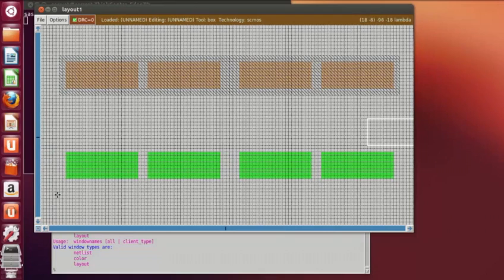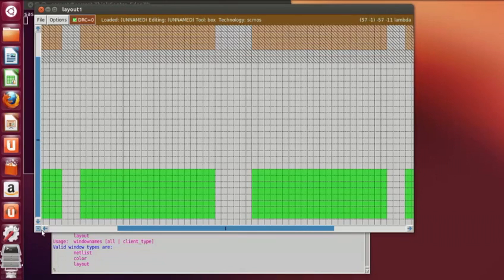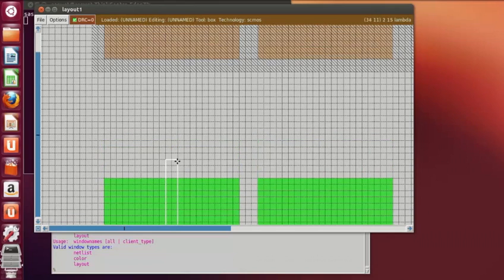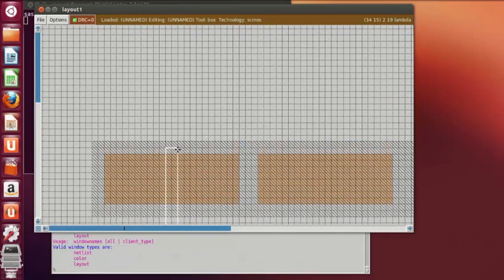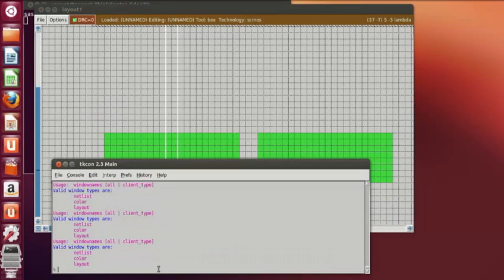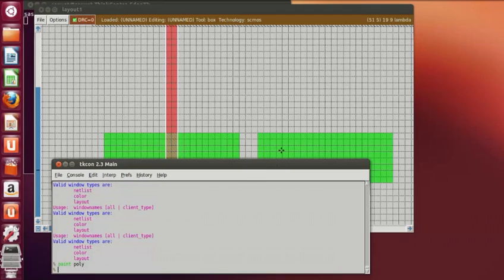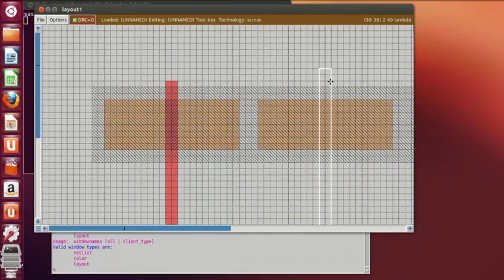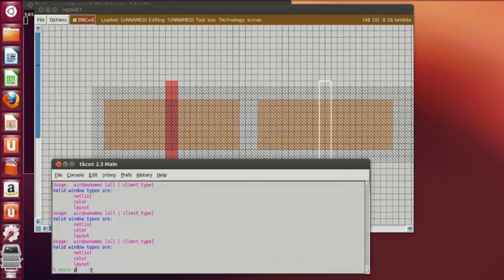for transmission gates. So in order to draw the inverters, first you have to draw the gate, that is the input. Zooming in helps us to find the width or draw according to the width. So this we have taken as 2 lambda. Okay, we can place over here. Now paint poly. Then again paint poly.